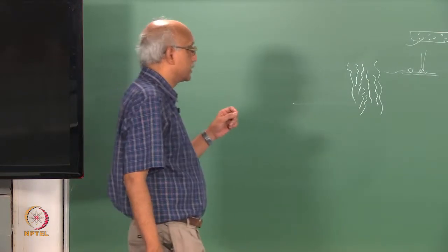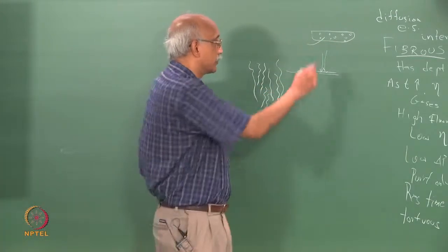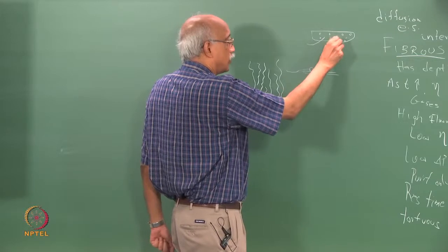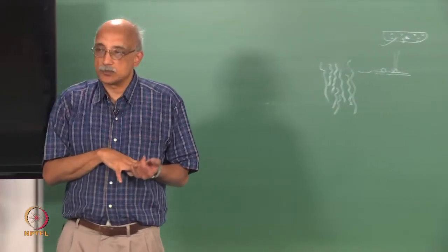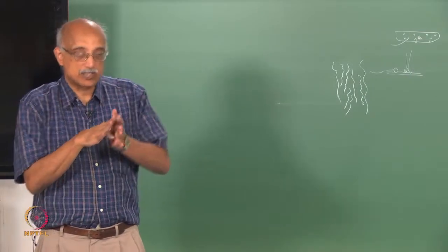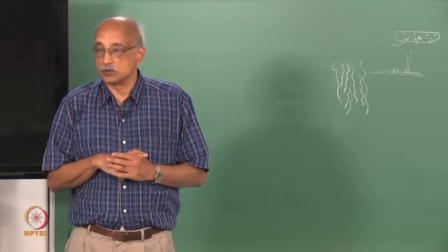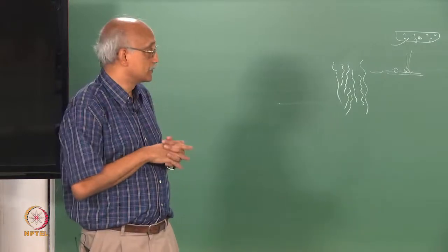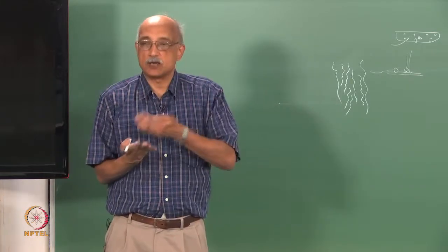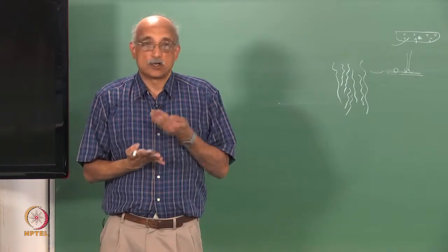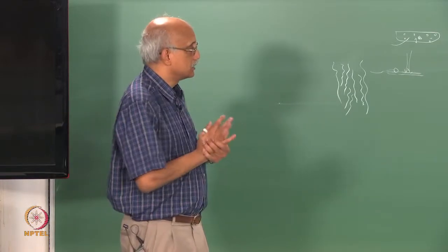Interception is important because again the mechanism, when a particle goes through the hole, whether it gets stuck in the hole or not depends on whether it actually contacts the outer periphery of the hole or the inner periphery of the hole. So, interception is another mechanism. Impaction is important because particles in a membrane filter will typically approach vertically in a normal direction, okay. And so, these are the three dominant mechanisms.